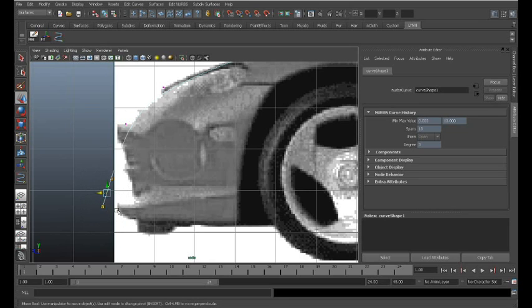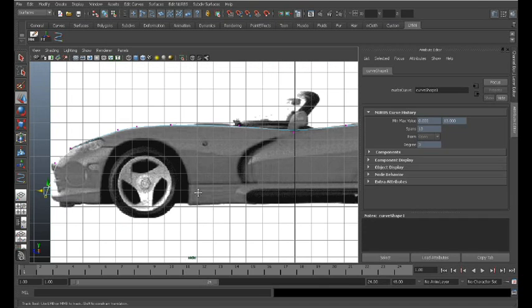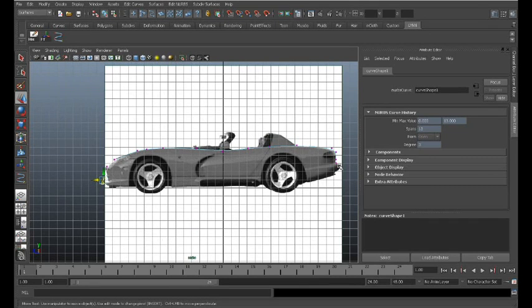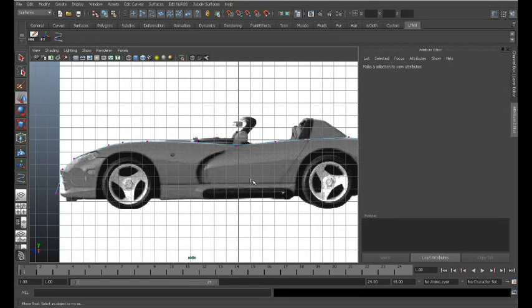Alright, and at the very end, this is important, you'll have some open boxes which indicate where the curve has started. That's very important because if you start on this end and plot curves, then your beginning points for that particular curve are on this end, and then when you go back to select both of those to create a patch, you'll get something that's twisted looking. If you do make that mistake, you can go ahead and reverse that. It's just a click of a button, and I will show you where that is a little bit later in case you need to reorder something.